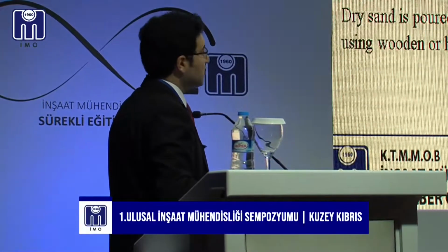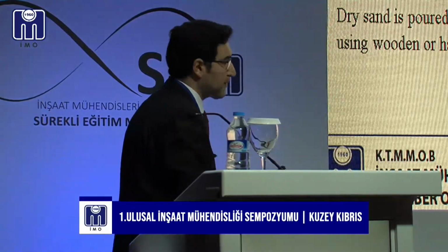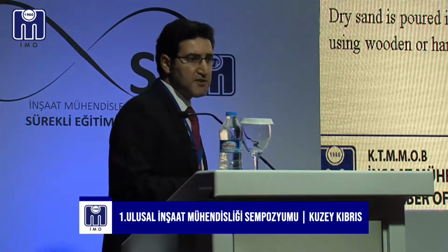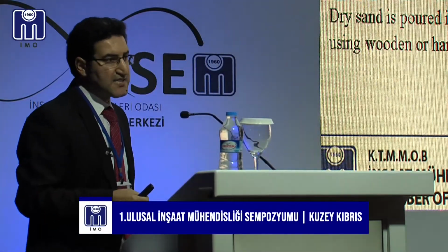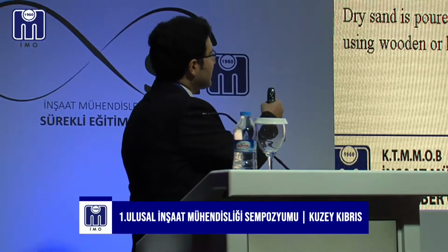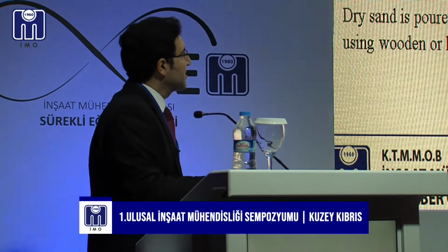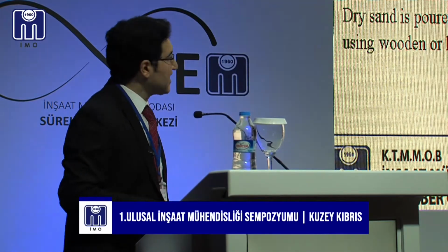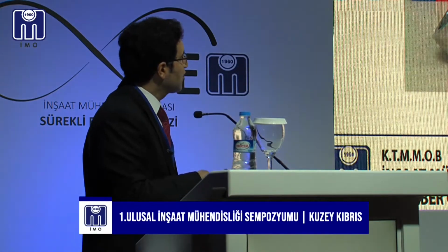To start, we want to work on the correction of the relative density, because the relative density obtained from the Japanese method calculation is a little different from the ASTM method. So for the Japanese Geotechnical Society, JGS, we consider evaluating e_min and e_max based on this method, as you can see.